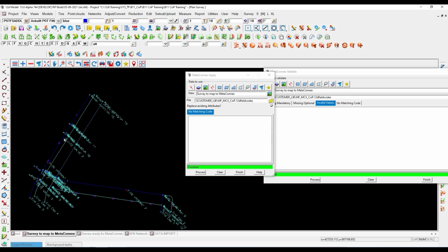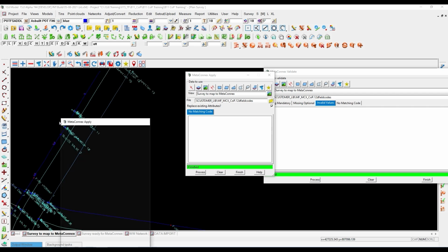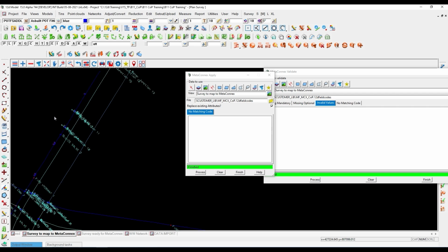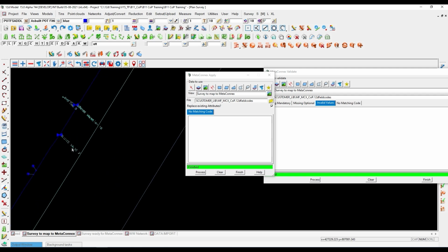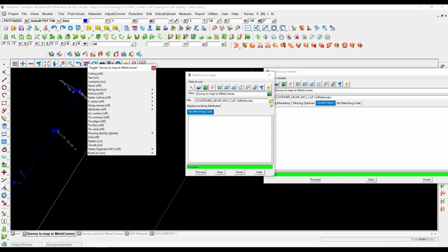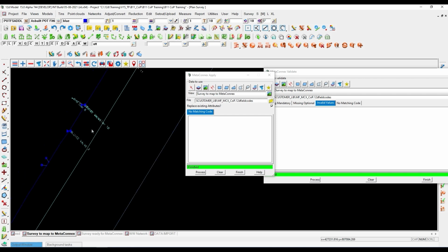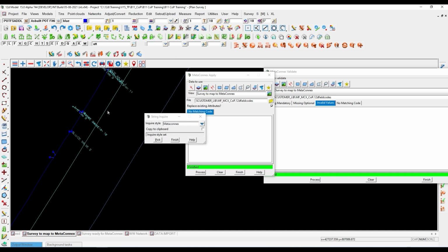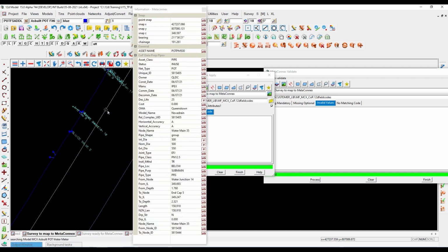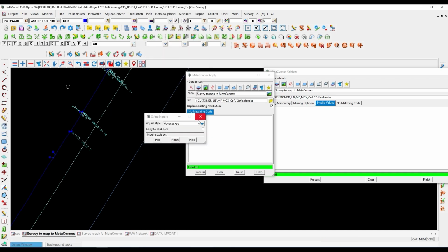you can see that 12D has gone and put a unique identifier on the point ID. So if I actually look down here, the point ID has been given the name. Now it's been calculated, the point ID. That is a part of the vertex. We can actually do the calculations and take that information there. And the same for the pipe. We've now given a name on the pipe, so we can do that. So if I just turn off my point IDs,